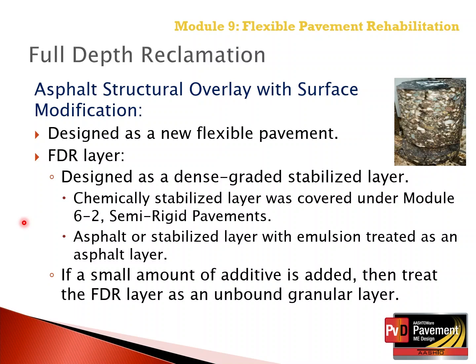It is designed as a new flexible pavement because we are totally destroying the existing asphalt layer, similar to rubbleizing jointed plain concrete pavement or continuously reinforced concrete pavement. So for the FDR layer, or the full depth reclamation, if it is designed as a dense graded stabilized layer, then it is treated as a new pavement, designed as a new pavement.